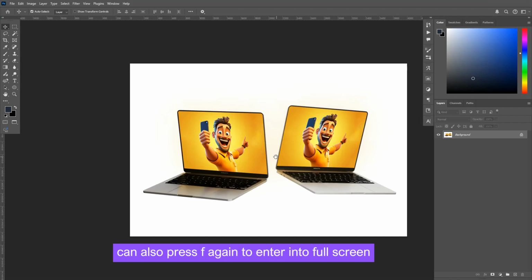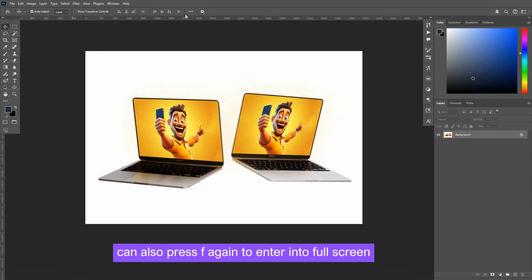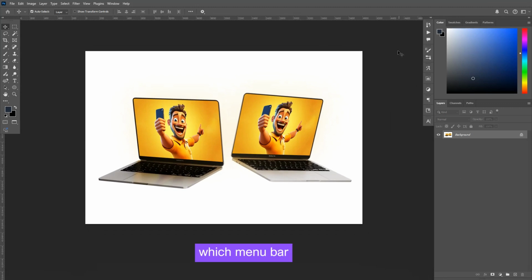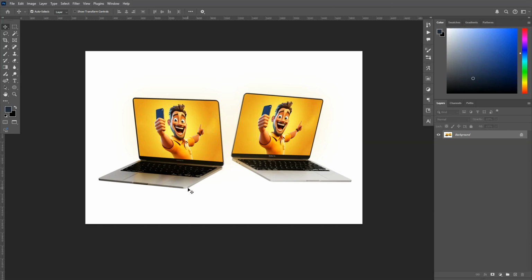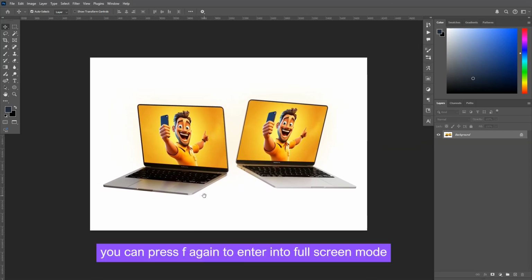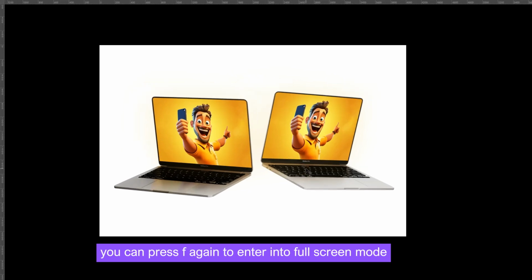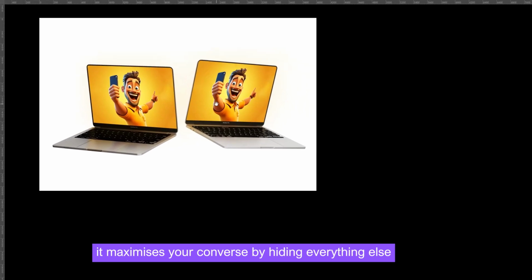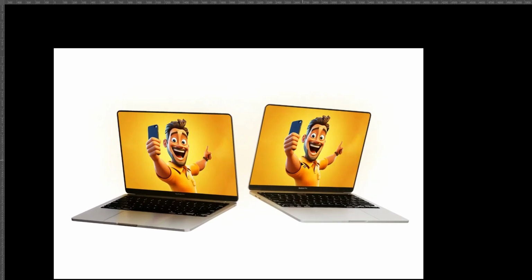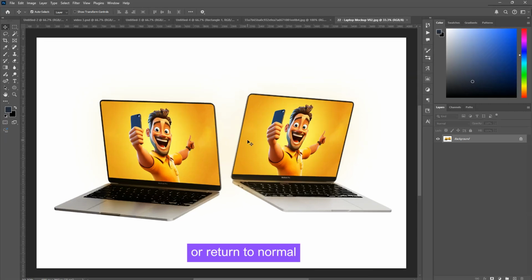You can also press F again to enter into full screen with menu bar, which expands the workspace but keeps the top menu. Also, you can press F again to enter into full screen mode, but here it maximizes your canvas by hiding everything else. You can press F again to switch between them or return to normal.